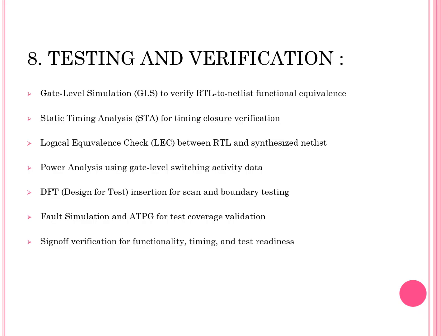Then, power analysis is carried out using gate level switching data to estimate dynamic and leakage power. DFT insertion, or design for test, adds scan and boundary scan features to make post silicon testing easier. Finally, fault simulation and ATPG are used to validate test coverage, followed by sign off verification, confirming that the design is functionally correct, timing clean, and test ready.